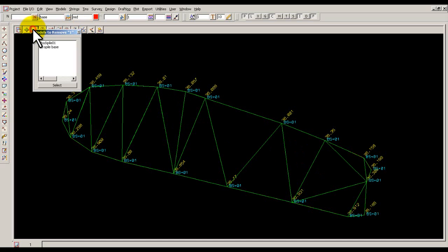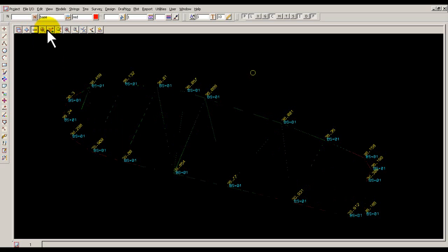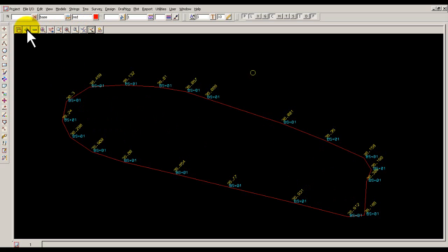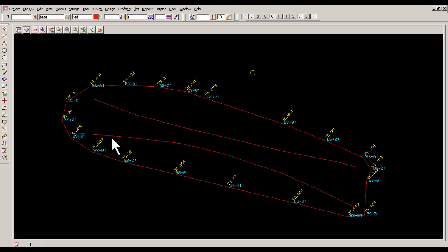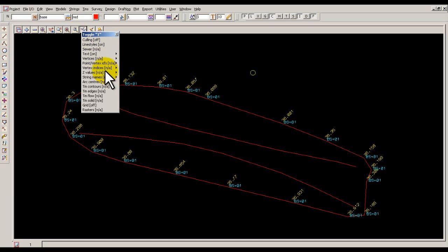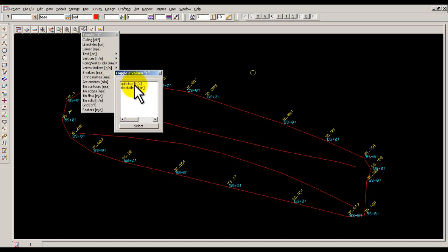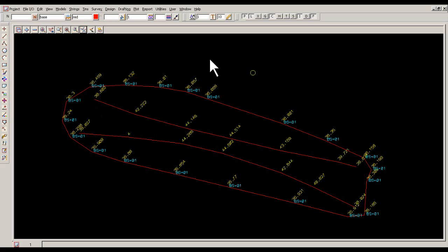So let's turn that TIN off. That's TIN stockpile base. Just turn that off and return to here. What we'll do now is I have added these S-pile points. I've added those in like so. You'll notice that they've got no data associated with them, so that's just a matter of going into the Z values and turning them on here if you want. I'm just doing this to show you various aspects of what happens and how the software functions.